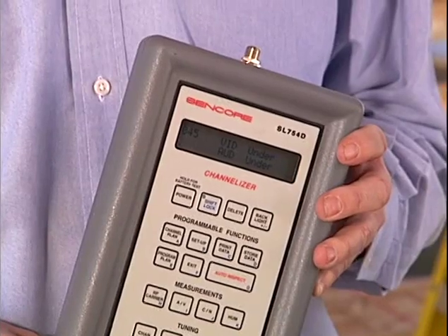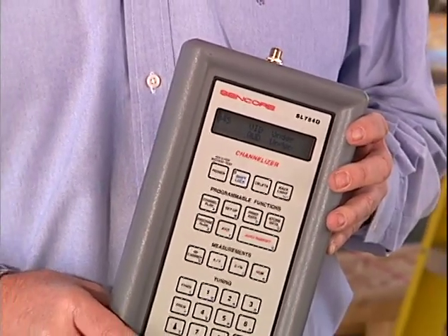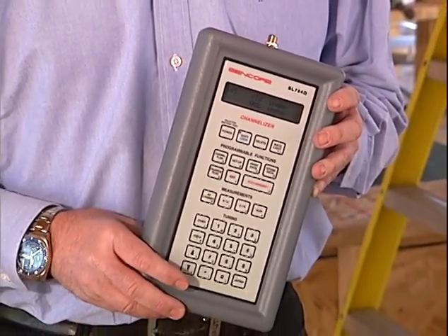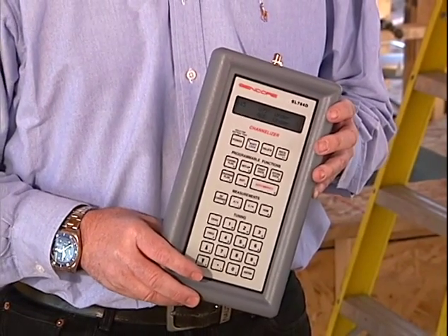RF signals can be easily measured utilizing a portable signal level meter like this. This unit will make any number of key measurements on any cable signal or off-air signal with an input range of minus 35 to plus 60 dBmV. It will measure RF and AF carrier amplitudes, carrier-to-noise ratios, hum levels, and so on. We'll talk more about working with cable service providers to ensure a successful install in Part 2. Next, let's look at some of the characteristics of coaxial cable in more detail.